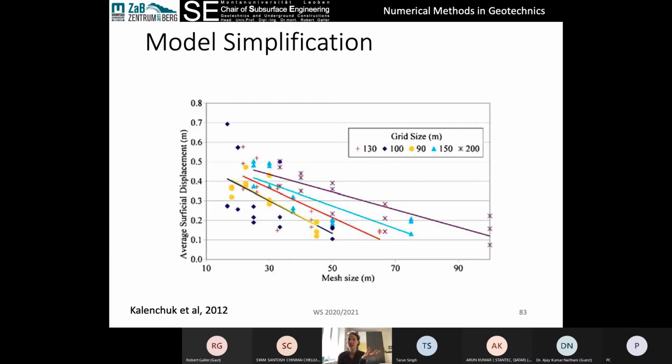So looking at what the effect of mesh size is. If we increase the mesh size, then we reduce the number of elements we're solving for, and our runtime is shorter. Does that actually affect our results, or are results much worse? At what point can we say, yep, the mesh size is optimized?